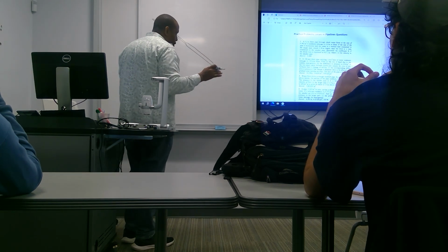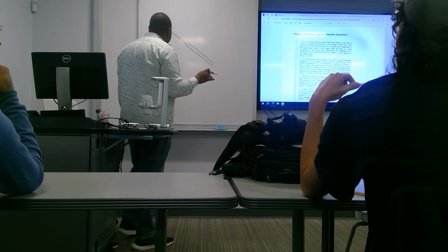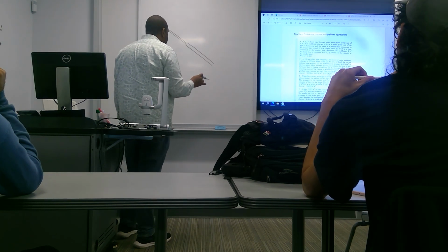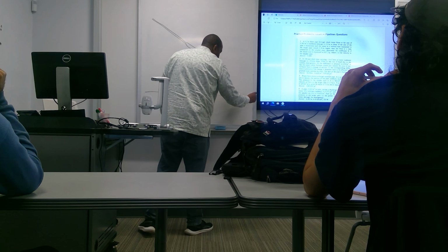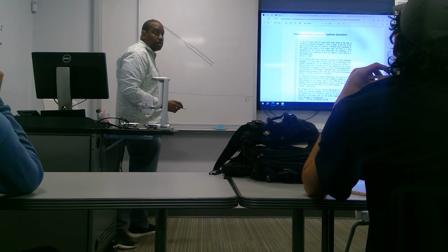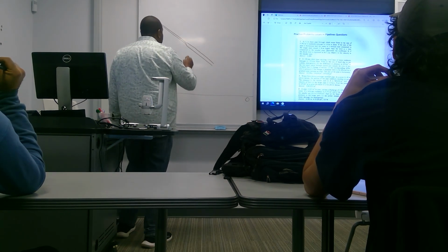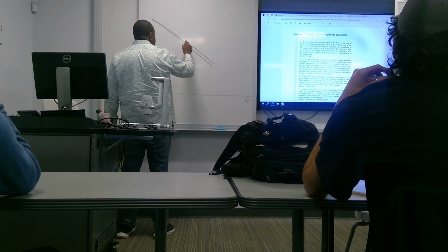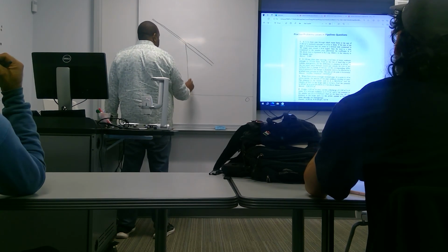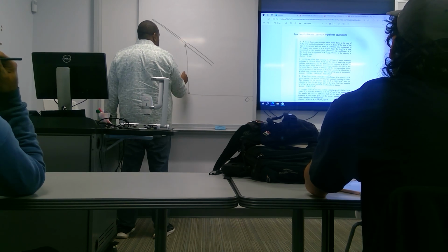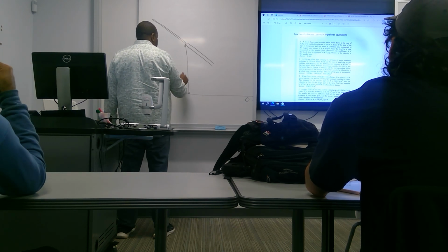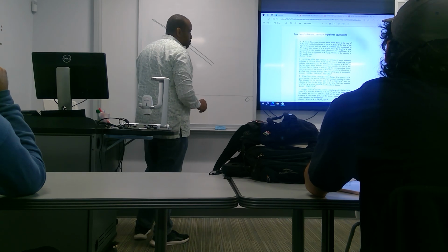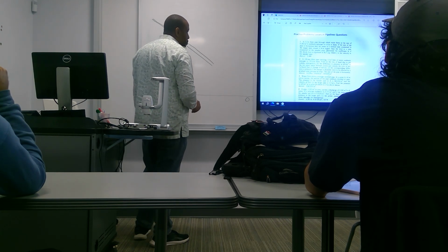It's doubling, right? So where's my datum? My datum is somewhere here, right? So from this point to my datum is what? 45 meters. Point A is supposed to be on top.